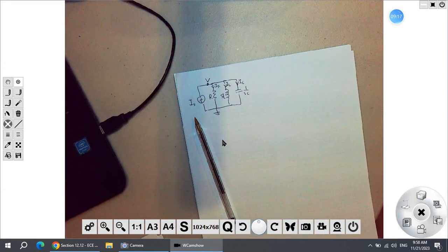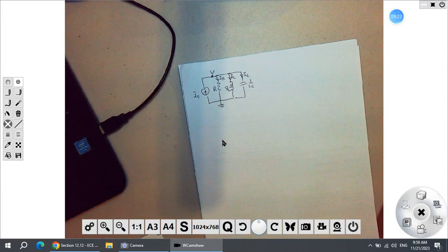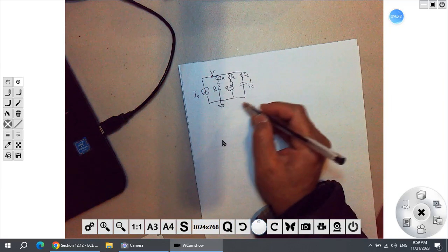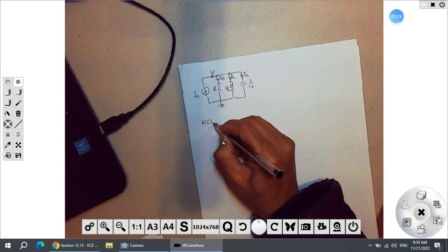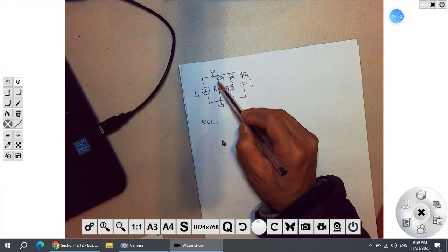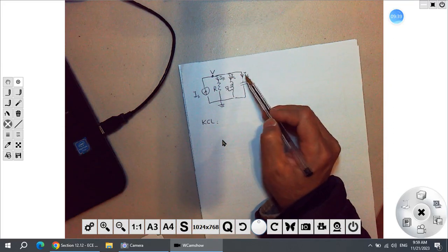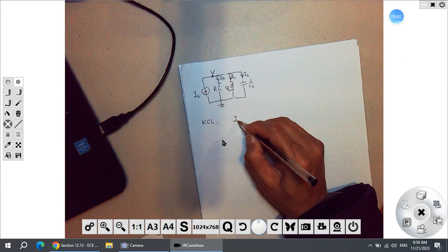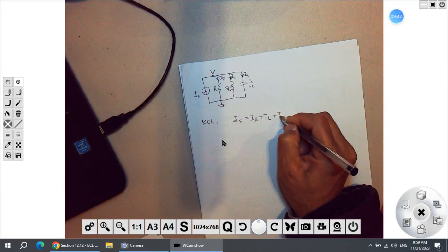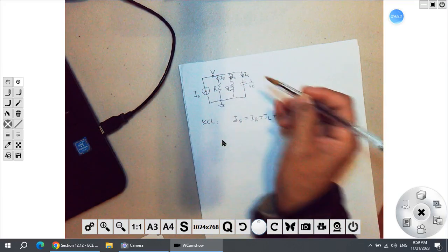Alright. So we have the circuit, right? Now we try to write the equation, and we can work the same as in the textbook. We use KCL. Here we have 4 currents. One is IS, which is given, and IR, IL, and IC are unknowns. The relation is IS equals IR plus IL plus IC, right? IS comes in and separates into 3 directions.